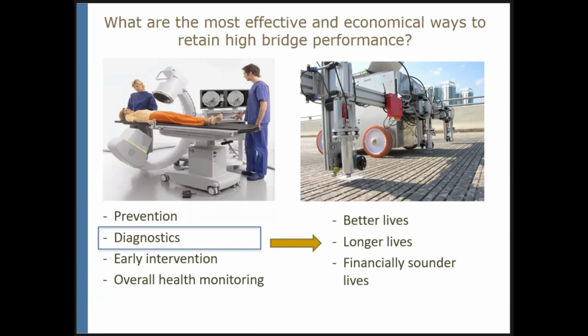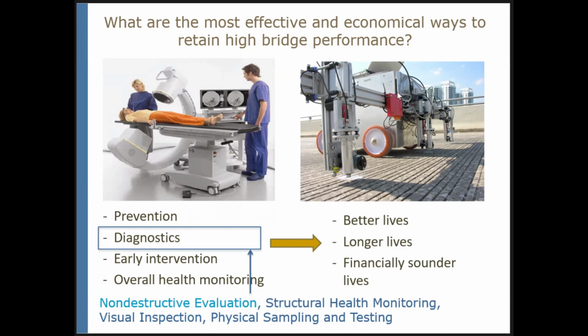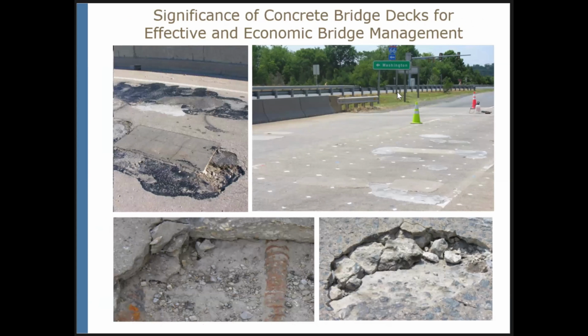We cannot speak about all of those, but I will speak today about one element, and that is diagnostics, and more specifically, I will concentrate on the use of non-destructive evaluation technologies for condition assessment and monitoring. Everything I will be speaking about, we have used in evaluation of all bridge components, but my talk will concentrate on concrete bridge decks. And the reasons are the following.